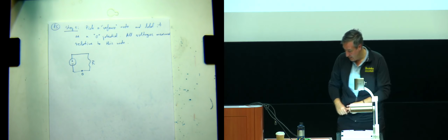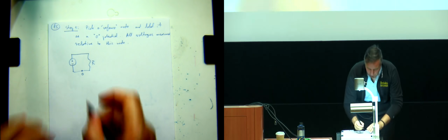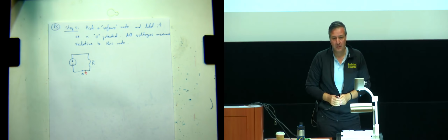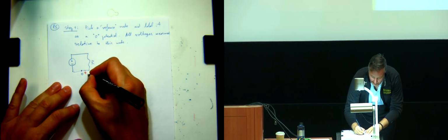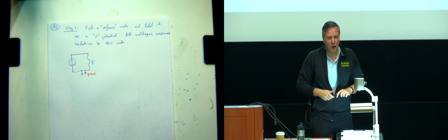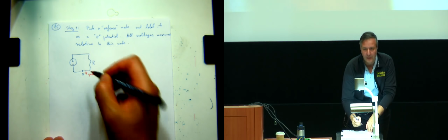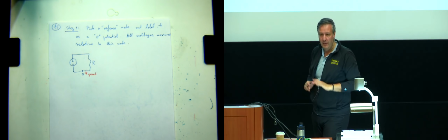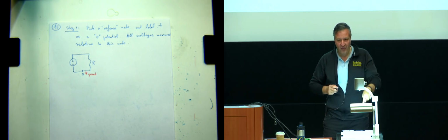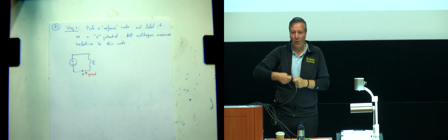Now, you'll see in some circuits, people add a symbol like this, and they call that ground. I'll try not to use that symbol because many people get confused, thinking there's some current flowing into that little stem. It's really not. It's just a label saying, hey, that node in the circuit is my reference node. I'm going to look at all of these.